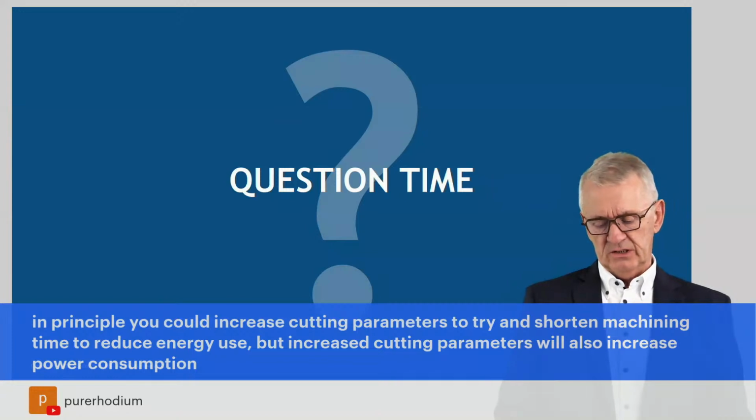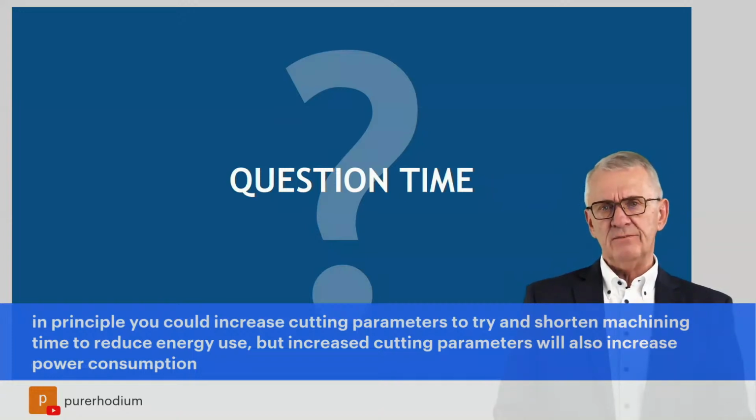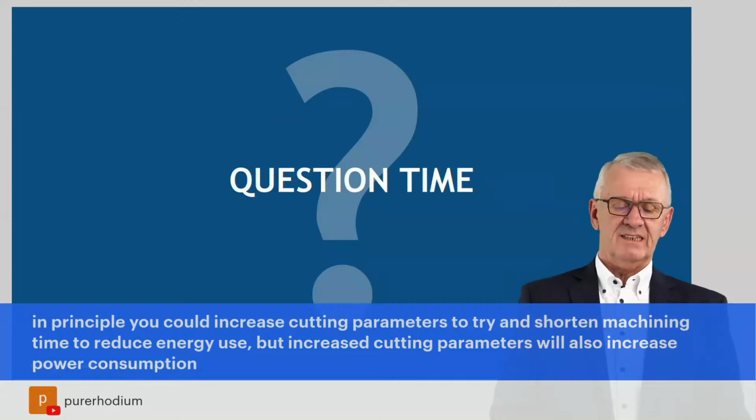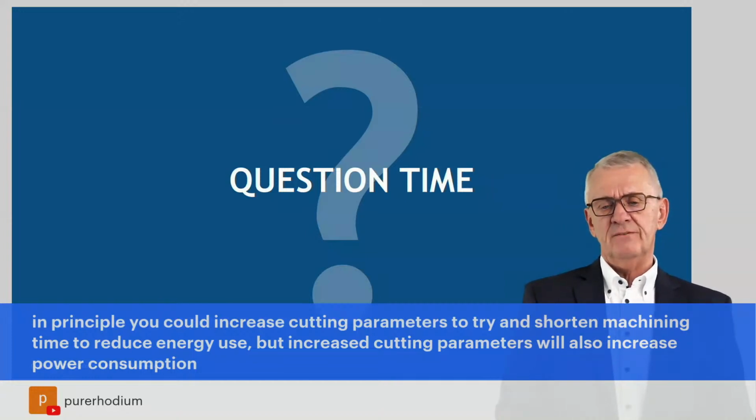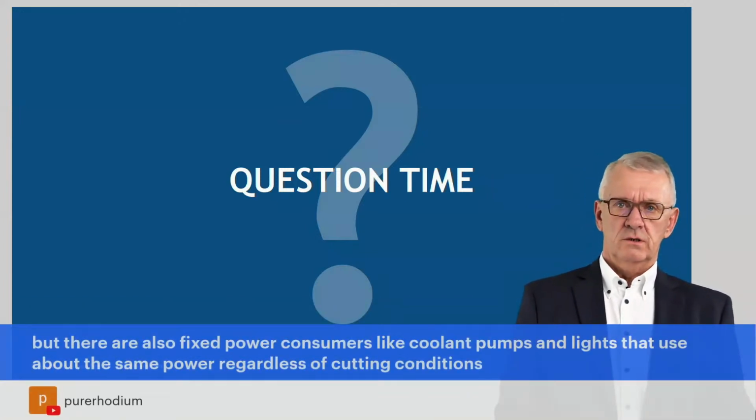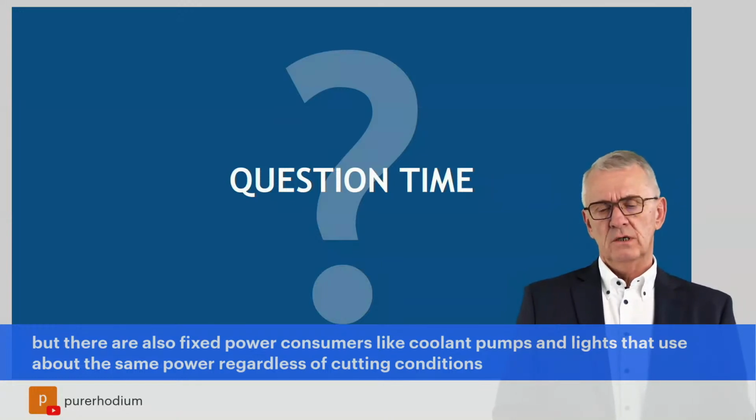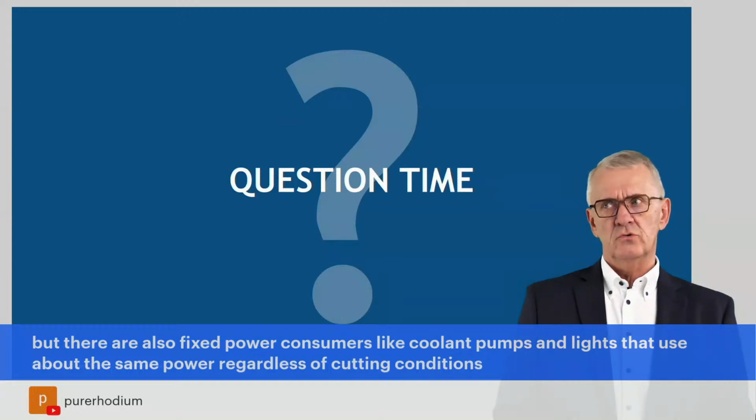If we start to change cutting conditions, the time needed to do the machining will change also. And then we have to be creative, we have to be intelligent, because if energy costs go up, my statement was you have to increase cutting conditions. But at the same time, at first sight, that leads to a higher power consumption. But if you combine things, and the fourth example I gave you was, if I increase my depths of cut and feeds, I reduce my costs. And you have to combine these two now. It's about which cutting conditions you increase and which you reduce.